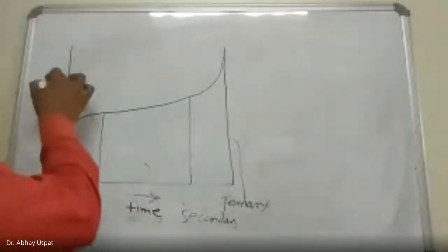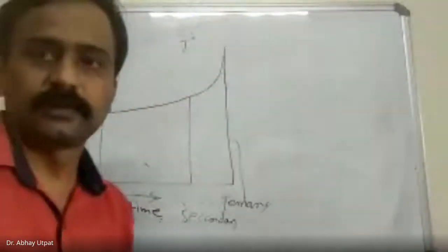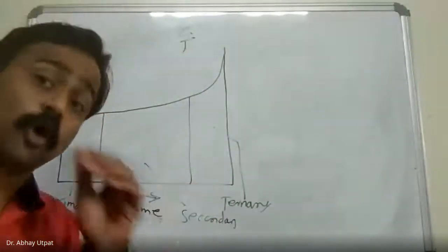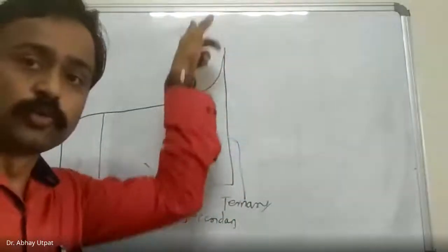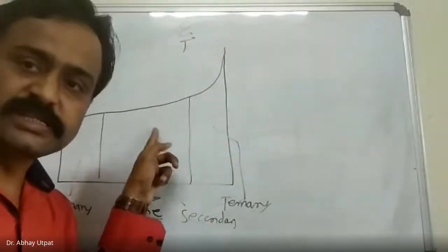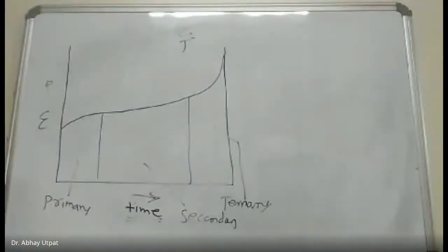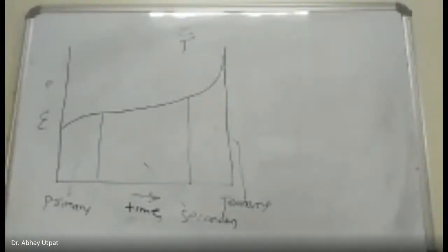Now, I told you, if you keep stress and temperature constant, it will remain so for a long time. But if you increase either of the two, there is a change in this creep curve. In the examination, many times the question was asked: draw a neat sketch of the creep curve, or explain the mechanism of the creep curve, or only the figure, draw the effect of stress and temperature on creep.